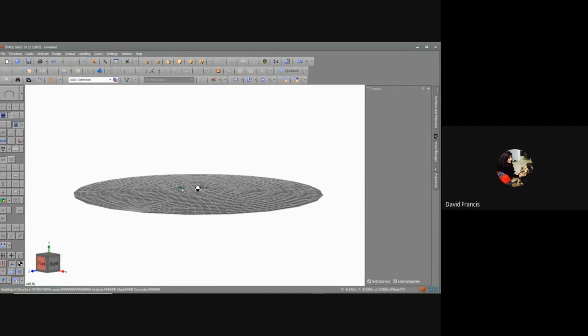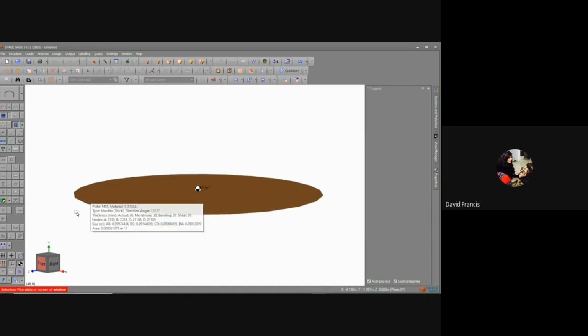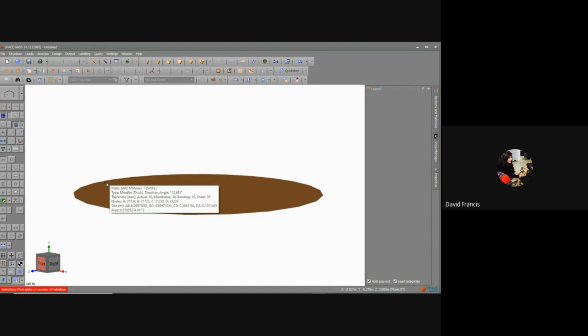If I now want to create a subgrade modulus of elasticity restraint, reaction, whatever you want to call it, for the support of the structure, it's going to be a subgrade elastic support for the base of the tank. I've got it isolated graphically. If I do Control A, and there were members and nodes as well, it would give me the choice, but they're just plate elements, so it automatically selected them.